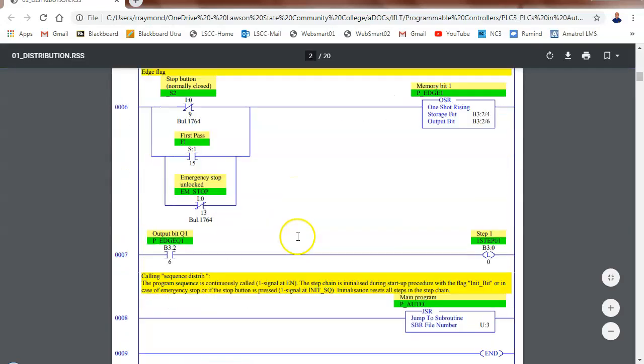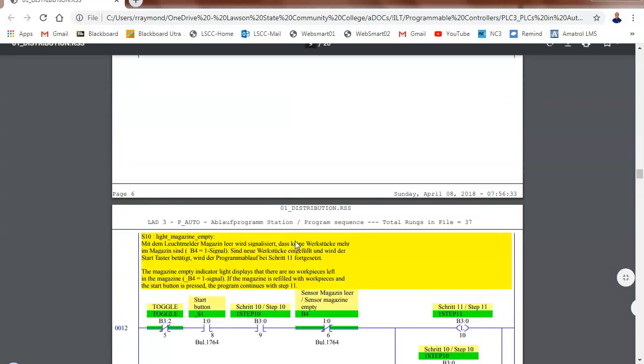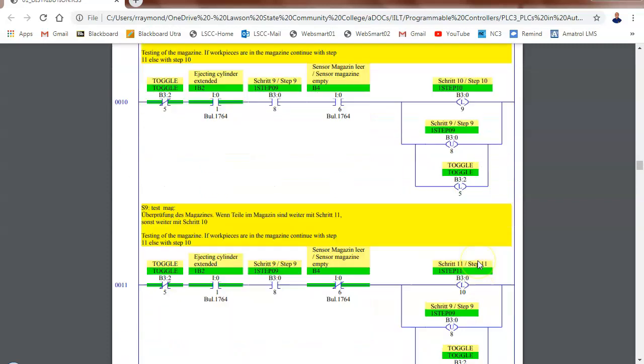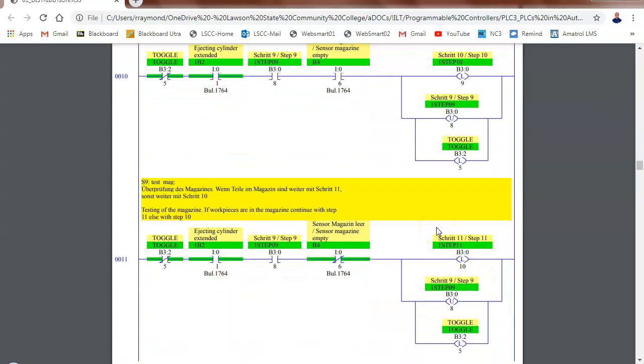So we'll talk about this later on, but let me get into the section called auto. Can you see what they're doing? So this is the way they set up a sequence. Here they latch this output, they unlatch that one, they latch this one, and that's basically the way they're going through the sequence. They want to make the robot go from this side to that side. Well, here you would latch it, and when it comes over here, you want it to automatically go back. So you hit over here, and then you'd unlatch it, right? You understand that? So you see these latch and unlatch.